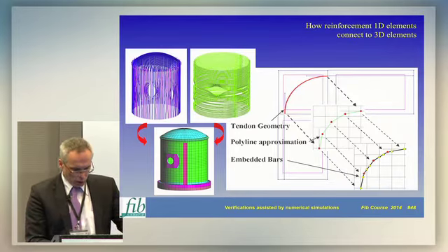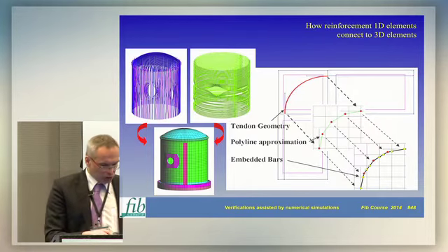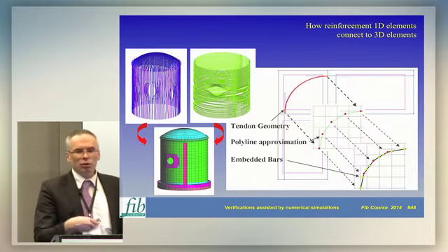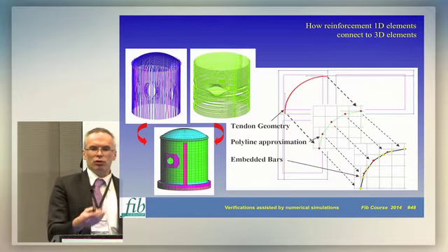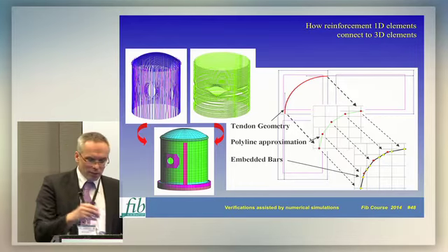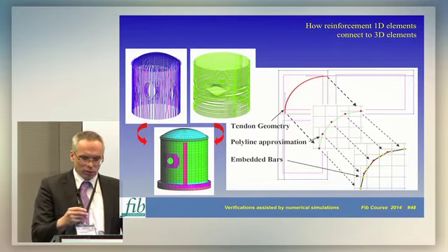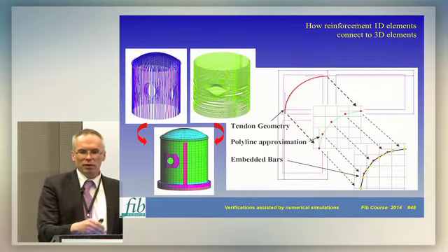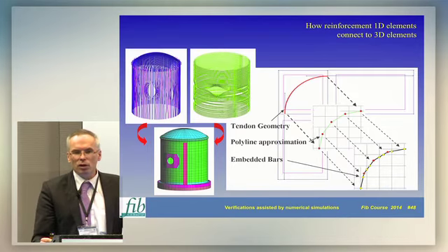So any deviation of the pre-stressing tendons can have an important effect. Now, what is, I think, important when applying nonlinear analysis to reinforced concrete structures or pre-stressed structures like this one, it is very important to have a good representation of the reinforcement and good representation of the solid model.